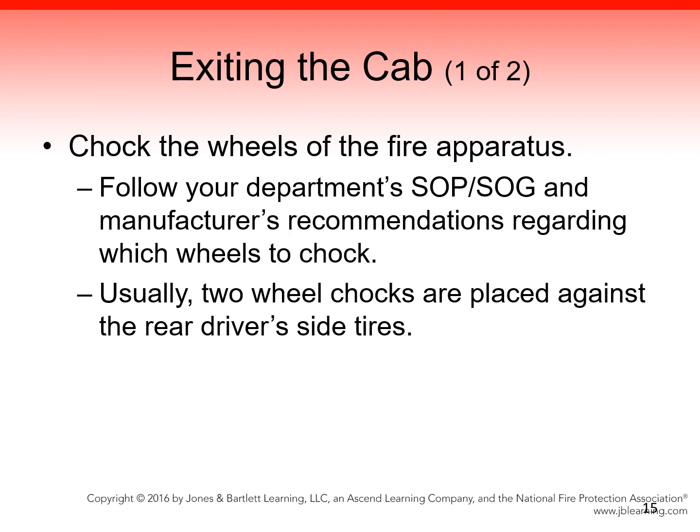Exiting the cab. Your first task upon exiting the cab of the fire apparatus is to check the wheels of the fire apparatus. Follow your department's standard operating procedures or guidelines, SOP and SOG, as well as the manufacturer recommendations regarding which wheels are to be chocked. Usually two wheel chocks are placed against the rear driver's side tires. This is necessary in case the fire apparatus moves during the incident. It will be stopped by the wheel chocks.